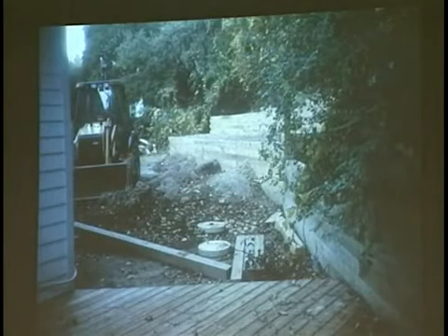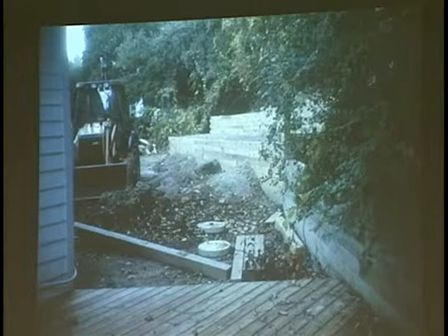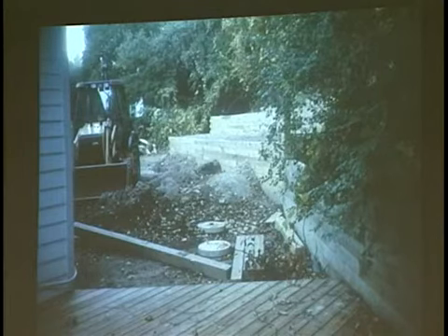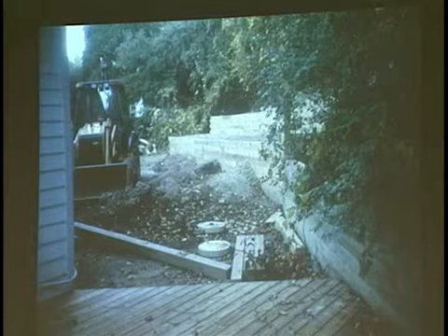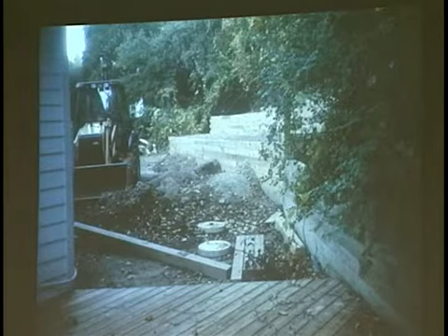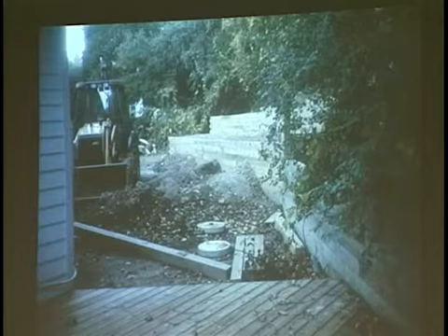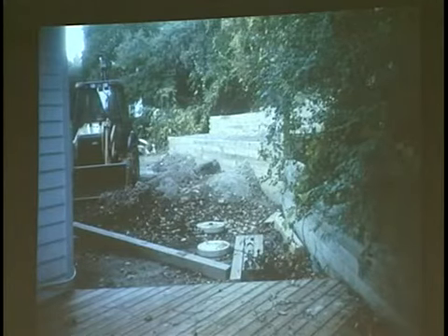Similar situation on this one. Rusted out steel septic tank underneath this deck caved in. This gentleman had one leach line in the driveway area here that was, number one, less than 100 feet from the lake. Number two, it was below the 10-year flood elevation of the lake. Appendix 75A says leach systems are unacceptable below the 10-year flood elevation.